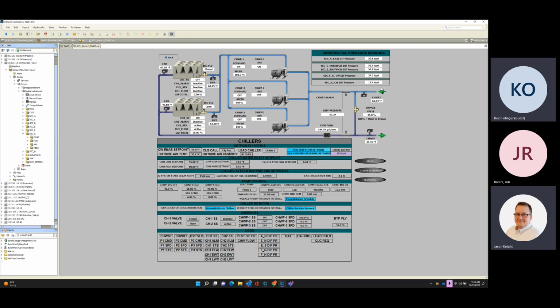There are a lot of temperature complaints every day. The temperature complaints are because the cooling set points are what we agreed to, 73.5 degrees. And you have teachers that get unhinged because their room is 73.8. The chill water valve's 41% open, and you're 0.3 of a degree above set point.